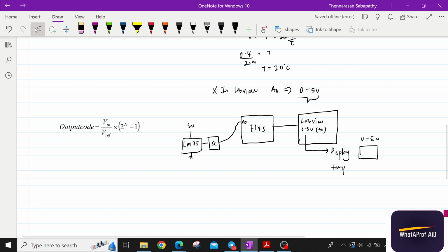Okay, so here you have 14 to 22, correct or not? Here you have 14 degrees Celsius, 22, right? Yeah, 22. 14 degrees Celsius to 22 degrees Celsius. So this will become your input, and then the output is actually over here, 0 to 5.